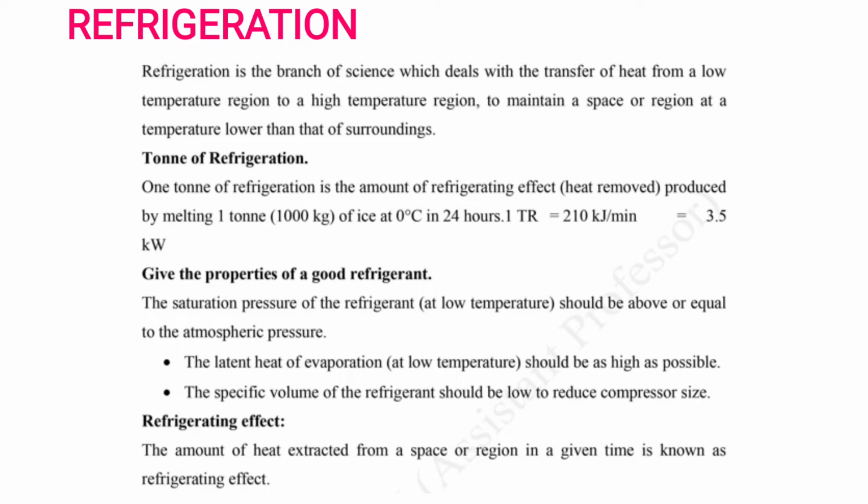Give the property of the refrigerant. The saturation pressure of refrigerant at low temperature should be above or equal to the atmospheric pressure. The latent heat of evaporation at low temperature should be as high as possible. The specific volume of refrigerant should be low to reduce compressor size.